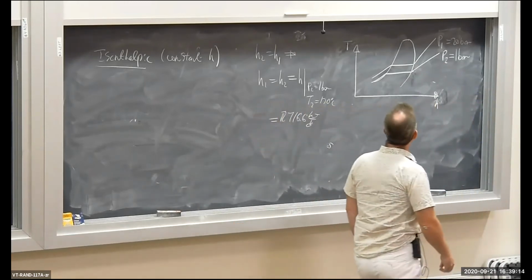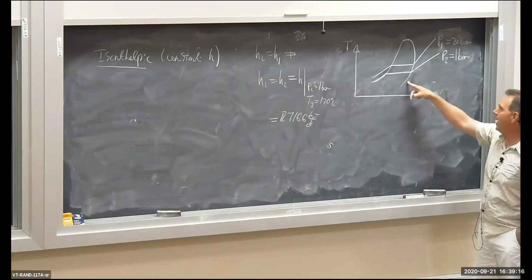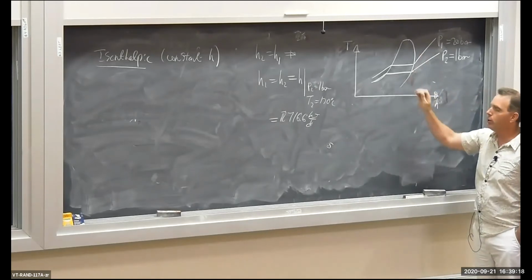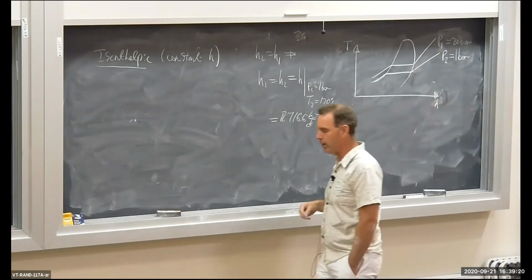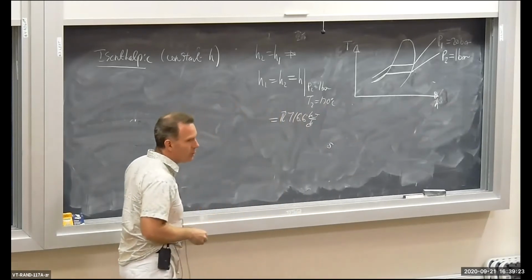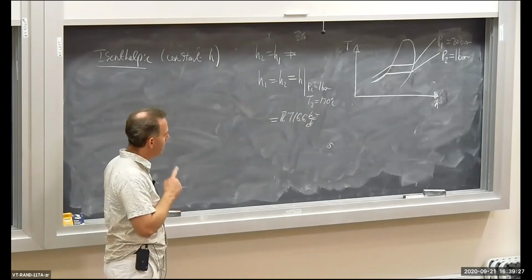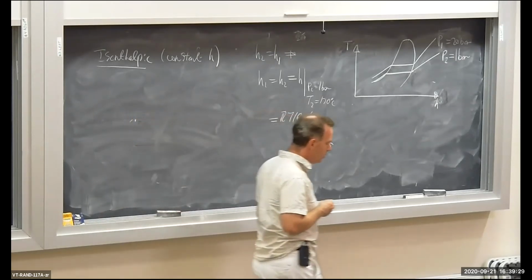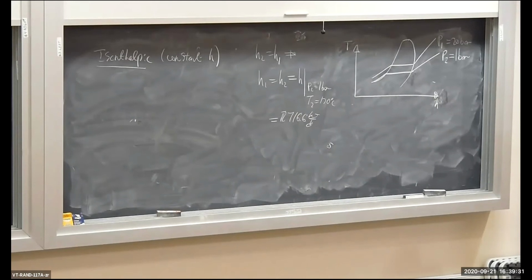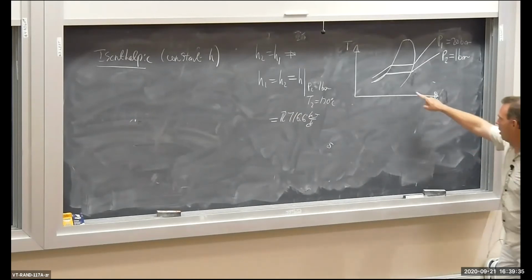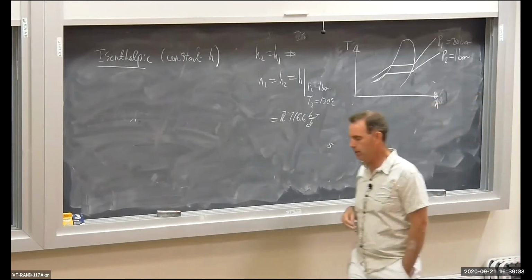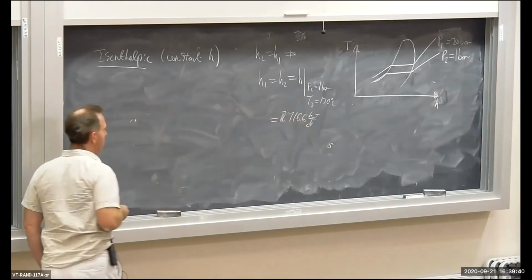Remember, the saturated vapor side of the saturation dome curves in this kind of strange manner compared to the TV and the TU plot. That's just what enthalpy does, all right? So I guess, strictly speaking, TH and TV aren't exactly qualitatively the same. You get this odd behavior on the superheated vapor side.